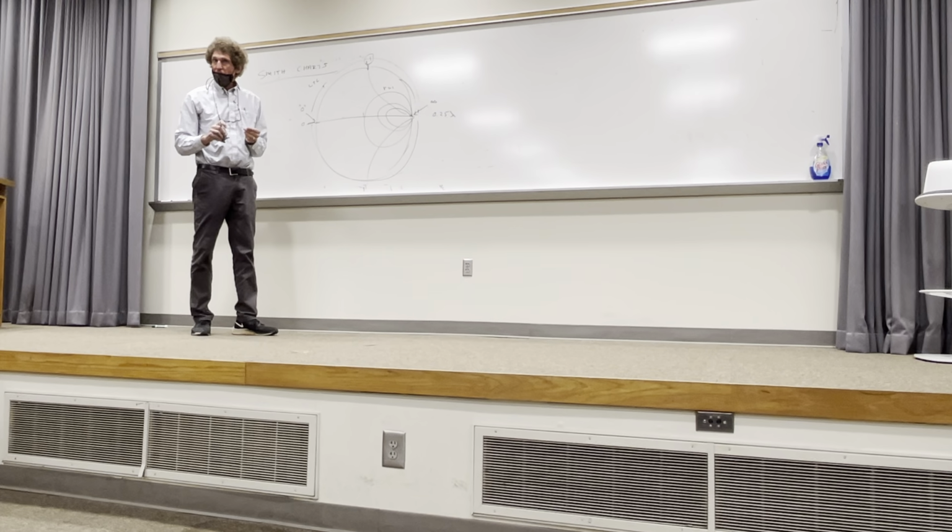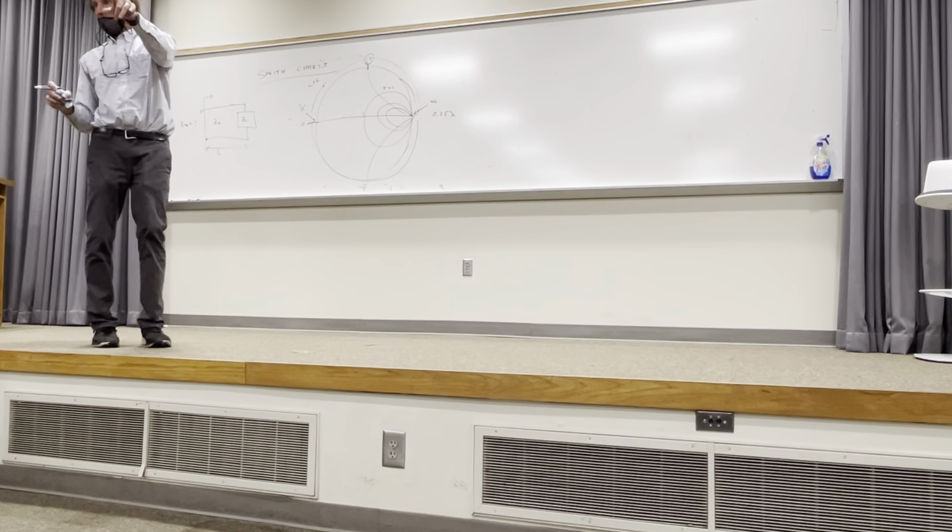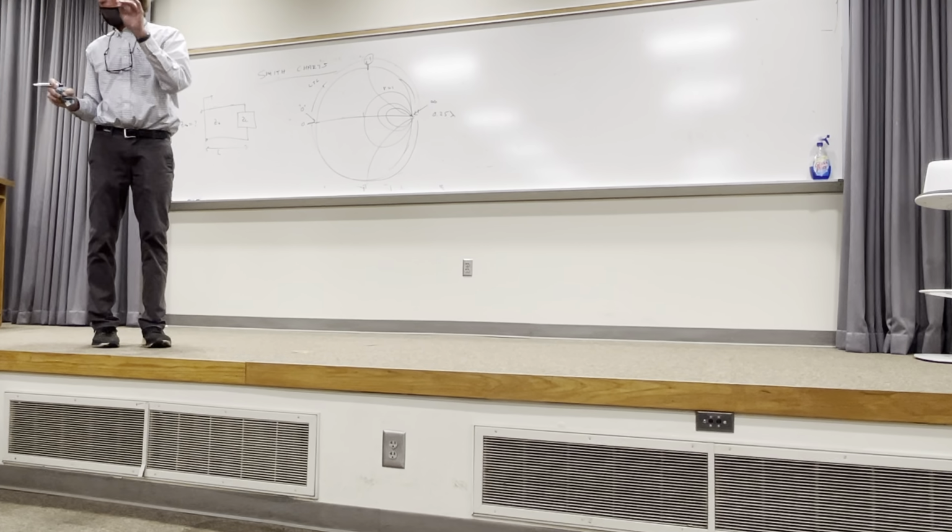All right. Now we do a problem. And we're going to do the same exact problem that we just worked in class that he asked me about, only with the Smith chart. Y'all remember? And you're going to see it's a whole lot easier to get the right answer. So we start. When we have a Smith chart, the first thing we have to do is get the normalized load impedance, and that's going to be ZL over Z0.